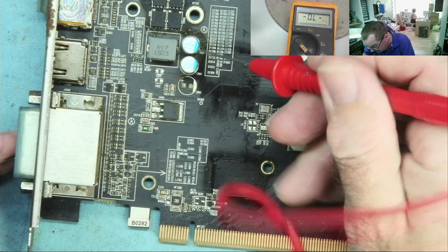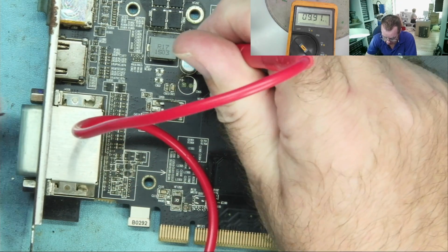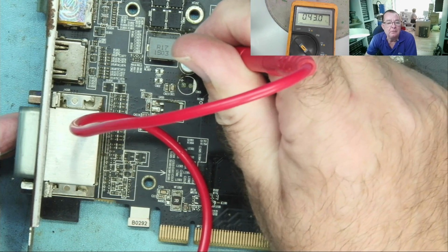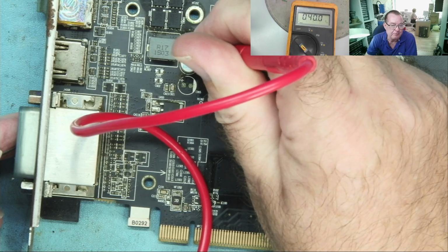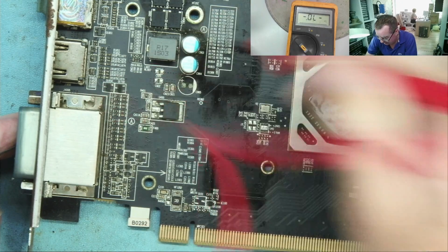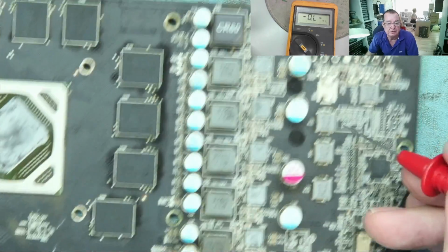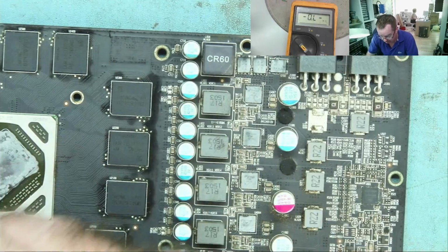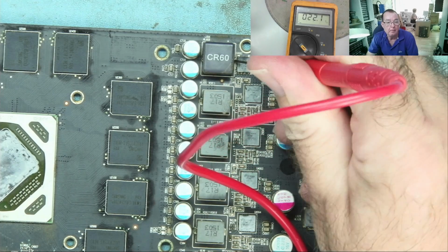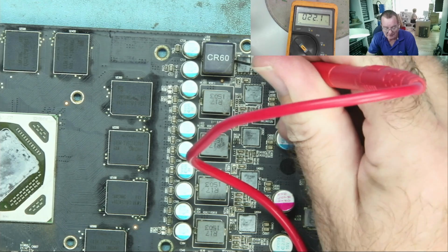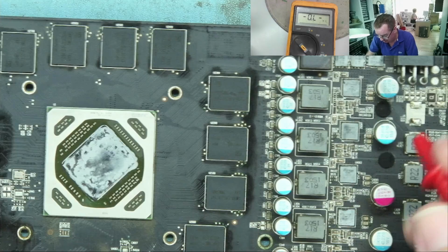We have a supply up here on the coil. That reads high. No, I've got it now. That reads about 40 ohms. 39, 40, yeah, 40 ohms. Could be RAM again, could be memory controller. Let's have a look on the other side. This might be RAM. 22, okay. We can do the same trick and figure out which one goes to the RAM.